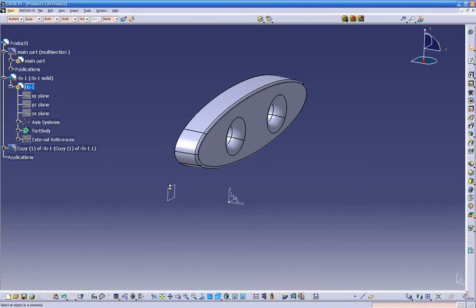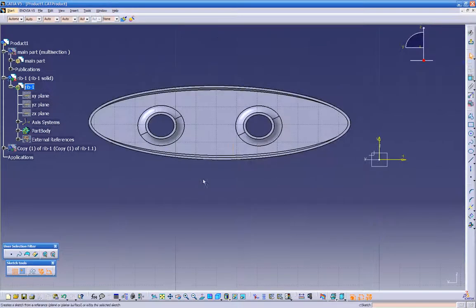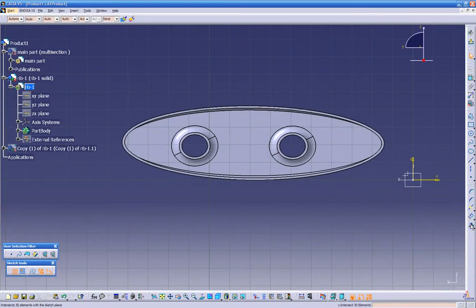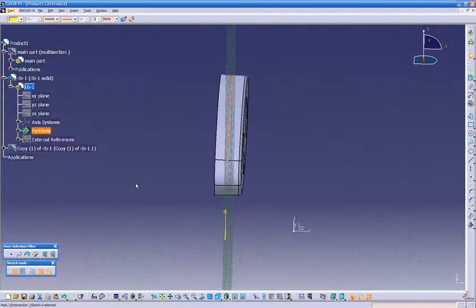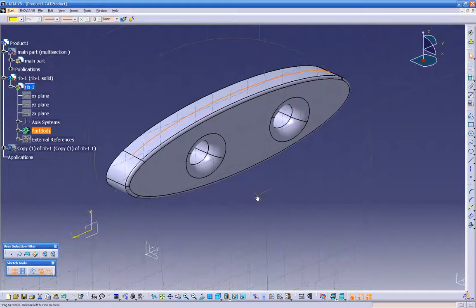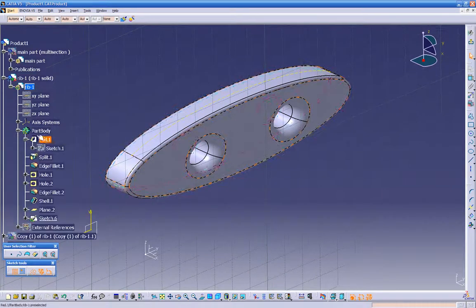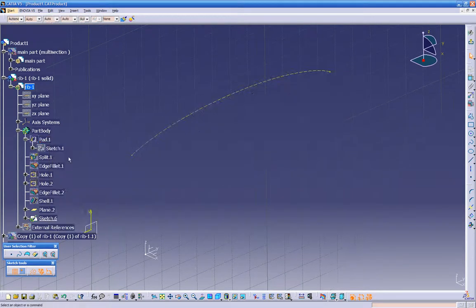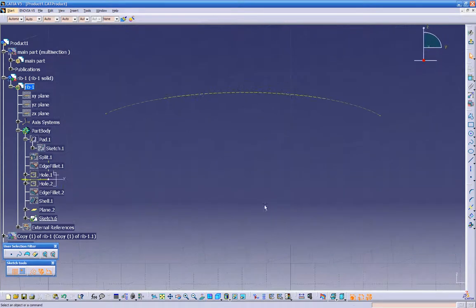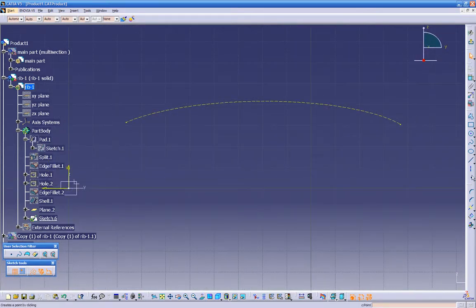Okay, so let's open a sketch, and let's go back again to this 3D element intersect, and we have our curve over there. We have to make sure we turn this option off. Let's hide the body. Let's see if we can get from here. Okay, let's do normal to view, and let's put a couple points. We use adjustable at equidistant points.